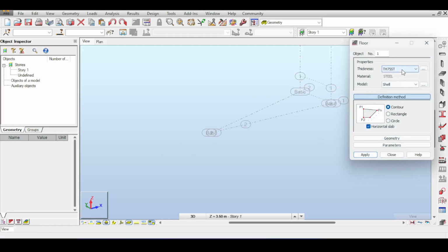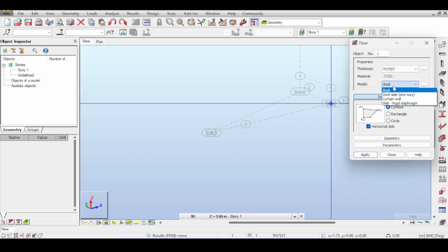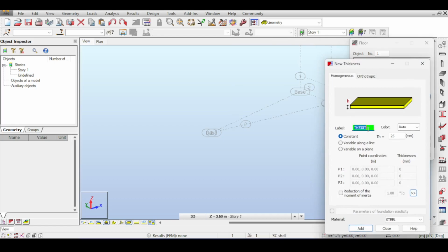All right, so what's the thickness of the steel you would be using for the staircase? And how do you design this stuff? Now, some of you like to design it as a little bar or a beam. I will just use a shell, because I talked about the design of shells in my silo video of the steel silo. So please take a look at that video, which is linked above. I'll use a shell. I'll assume a thickness of, I don't know, 10 millimeters, for example.